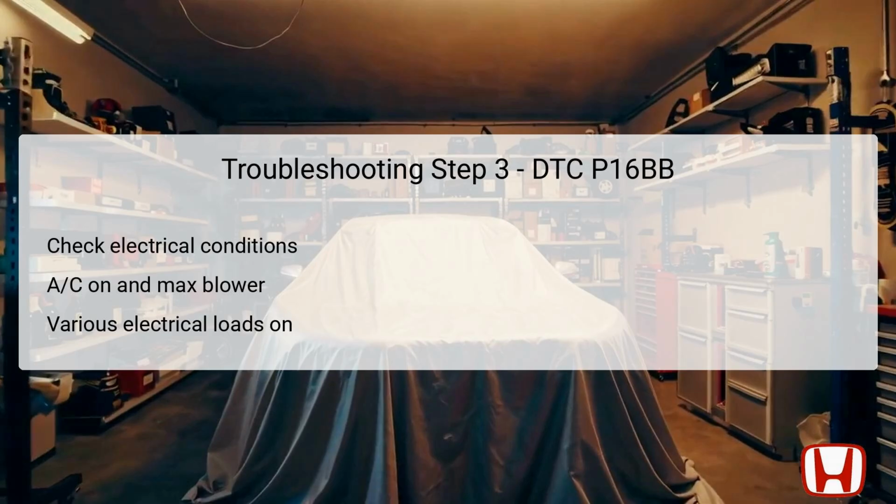Additionally, turning on the headlights at high beam and engaging the rear window defogger are essential steps. These combined actions create an environment for the alternator to function under simulated high demand, crucial for identifying any weaknesses in voltage output or electrical connections. The performance during this load test will provide crucial insights into whether the alternator and wiring maintain adequate voltage levels or if issues arise.